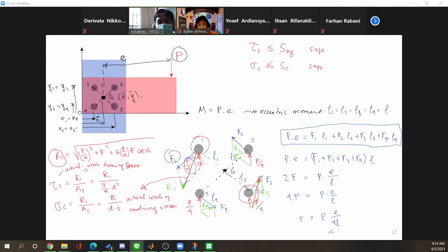Okay, let's resume. Let's make it shorter. Okay, let's resume this. For the eccentric joint, first we have to find the geometry, the center of geometry. Then next, calculate the eccentricity that is measured from the load to the center of joint. Okay, so please find this one.